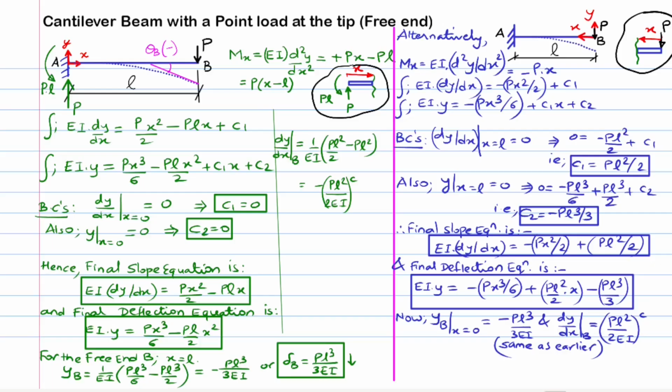The second method eventually permits us to skip the initial calculations involving the reactive force and reactive moment, and also reduces the number of terms in the moment expression of the elastic curve, and therefore in the succeeding two equations. The selection of the reference coordinate system location is hence a matter of convenience.